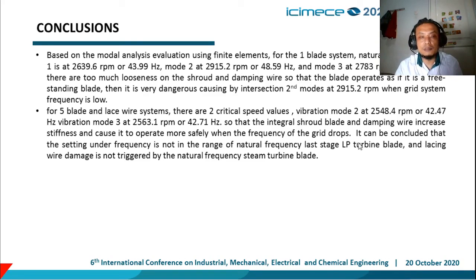It can be concluded that the under-frequency setting is not in the range of natural frequency of the elastic low pressure turbine blade, and the lashing wire damage is not triggered by the natural frequency of the steam turbine blade.